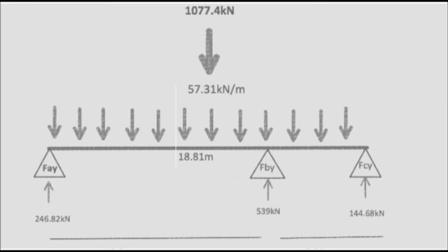Once the diagram was done, we began the calculations, multiplying the total point load by gravity and multiplying it by the length. Since the bridge was split in half, as Zainab previously mentioned, we had A being 6.6 meters and B being 10.8 meters, using these as the new lengths. To find reactionary force C, we used algebra to find the missing value.